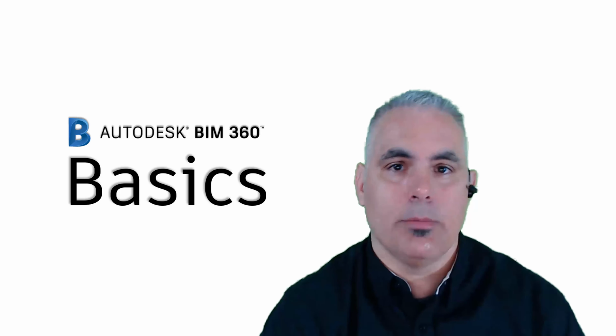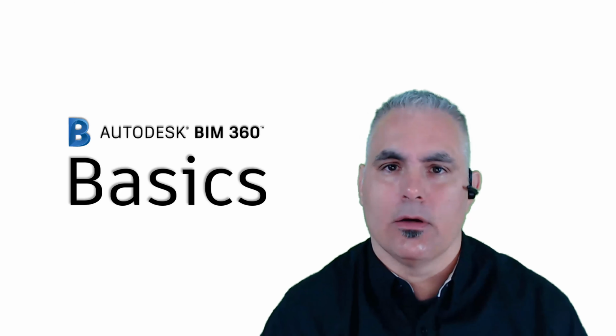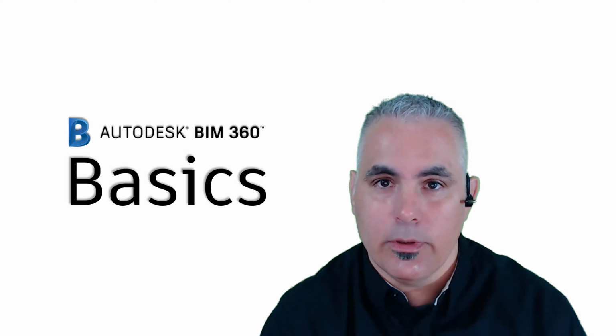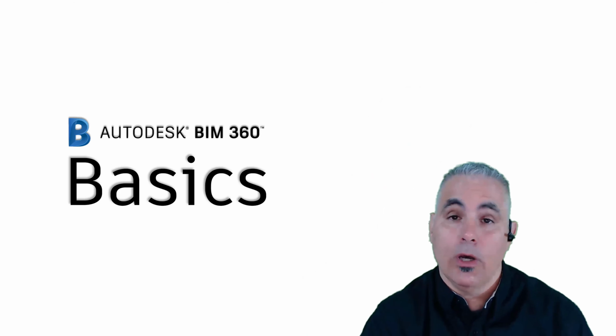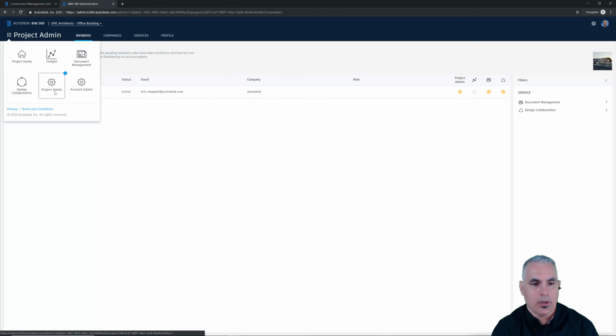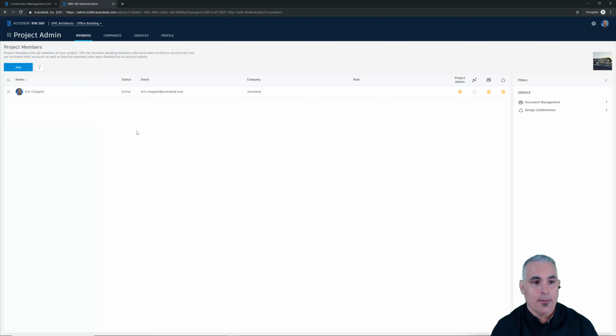Let's say you've just set up a project and you're ready to start inviting members into the project, people that are going to work on the project with you. How do you do that? Well, to start, you need to be on the project admin screen. To do that, you'll click the module selector and then project admin. You can see I've already done that.